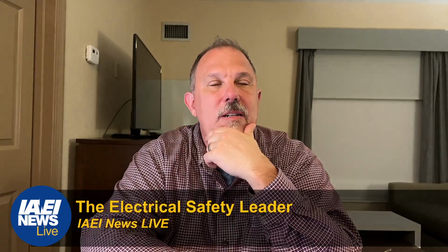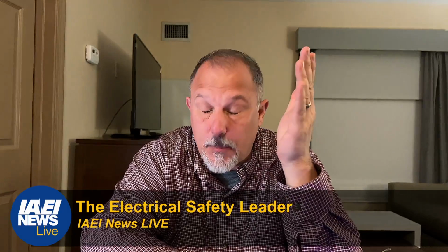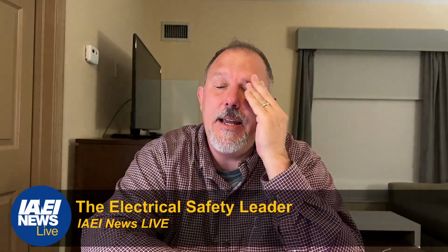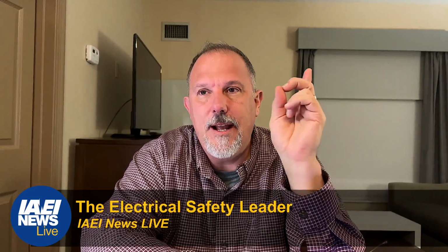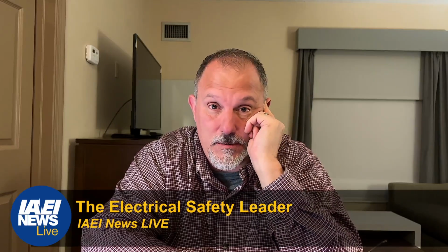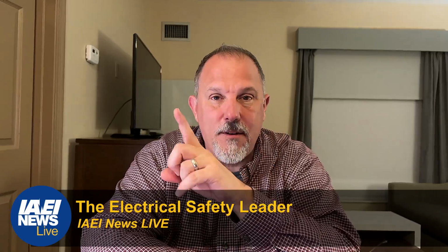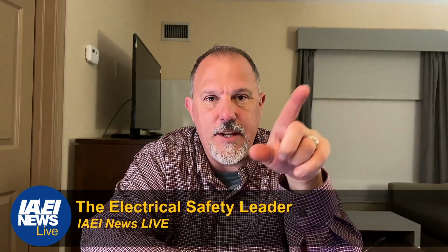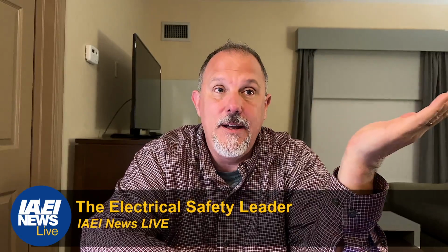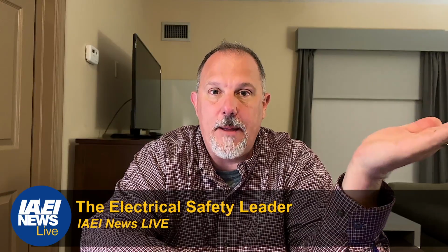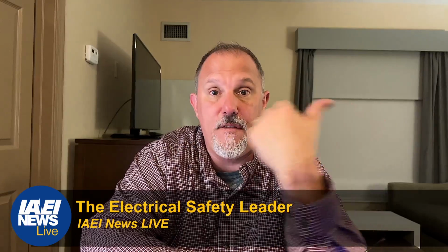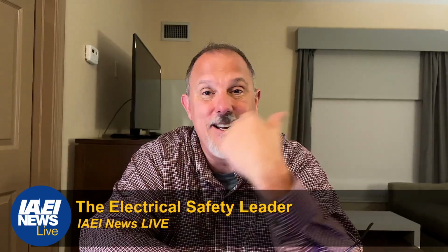Here's where, and we haven't fixed it, but here's the problem. If I have a panel board, say in a separate building, I have an outside circuit that feeds that panel board, and let's say that panel board needs a receptacle for servicing. How do I power that receptacle? I have one power feed going from one structure to another. That's a feeder that feeds that panel board. If I put a receptacle and I feed it from that panel board, when I turn that panel board off from the upstream overcurrent device, now the receptacle's dead.